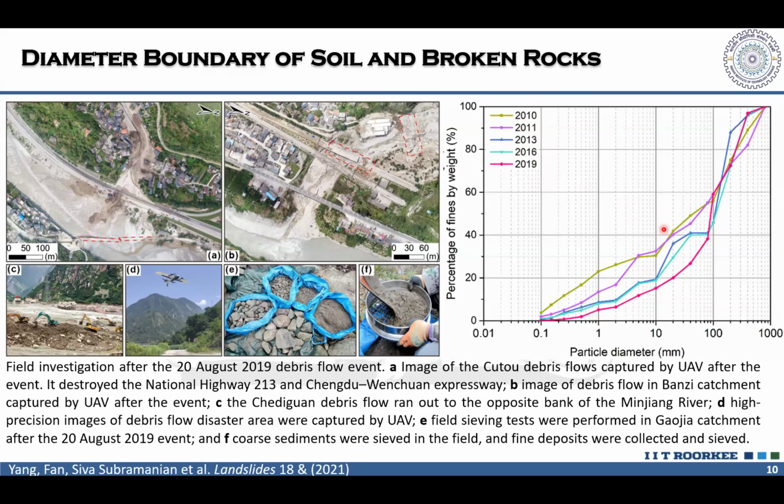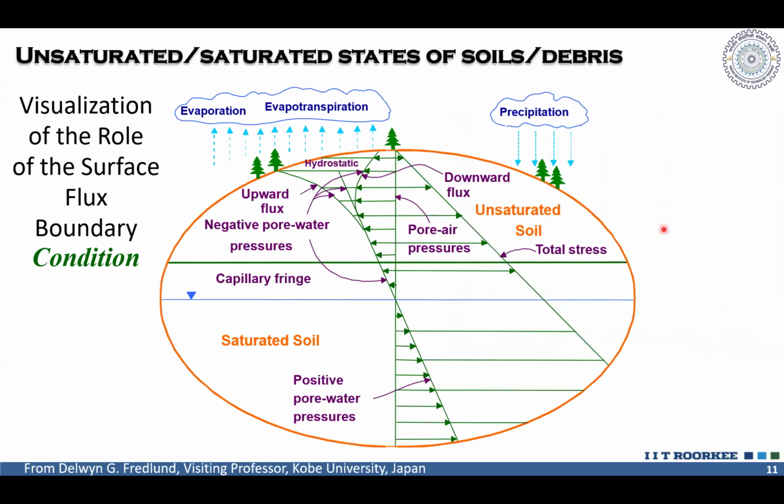There is much literature available for understanding the seepage as well as the mechanical characteristics of debris material. In addition, in the Himalayas, since we have these deposits all across the hill slopes, wherever we go, we sample the material, the grain size material, and we find the maximum of D50. More or less, it's always more than 10 mm in the Himalayas.